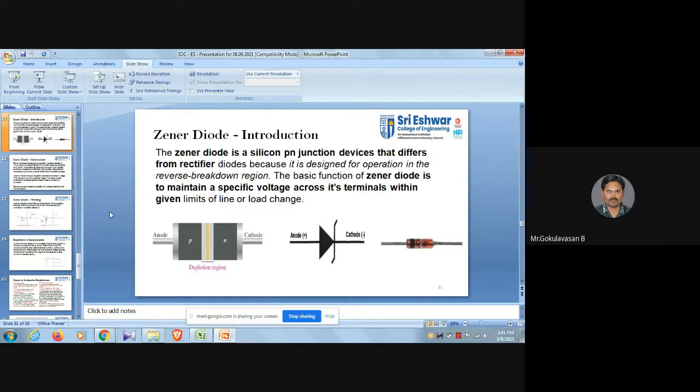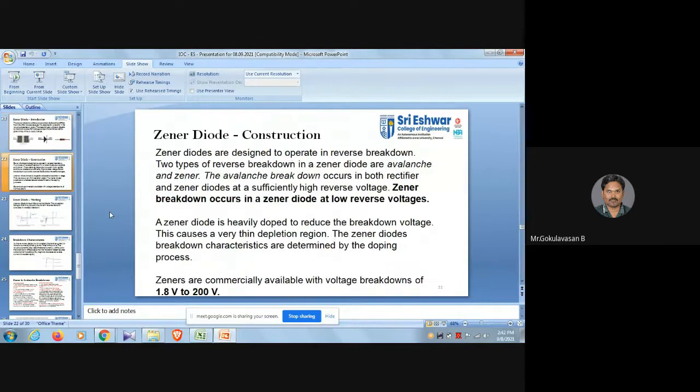Okay, I think you cannot guess that. See the black band, you can see it on one side, the left side of the diode. That particular side on which the band is available is the cathode, and the opposite terminal is the anode port.